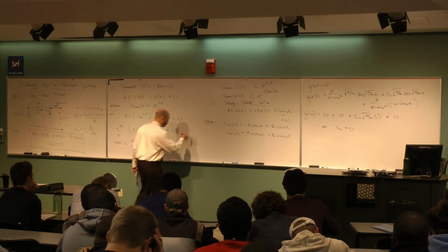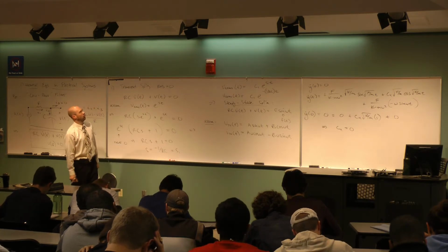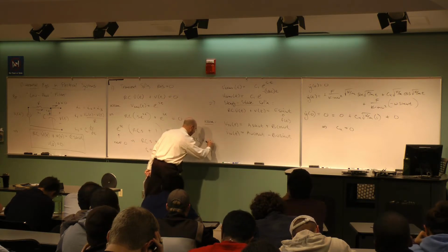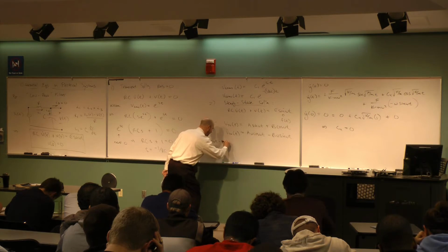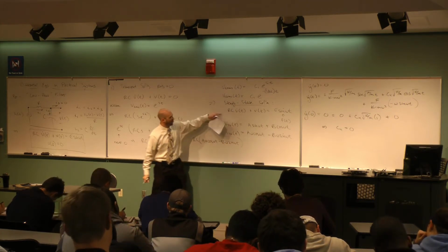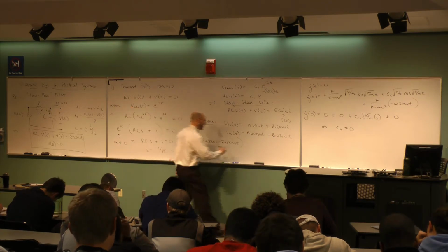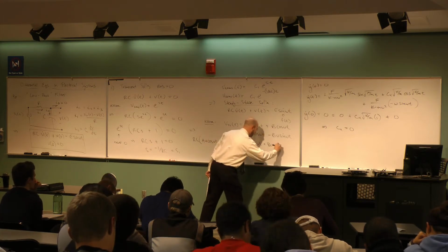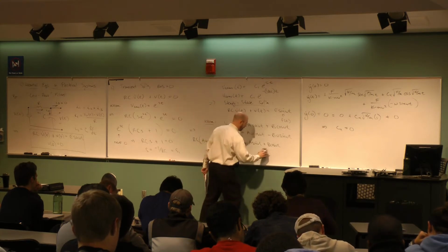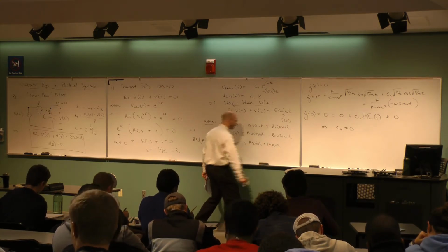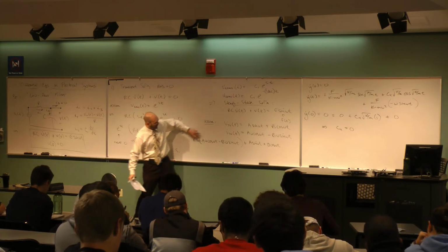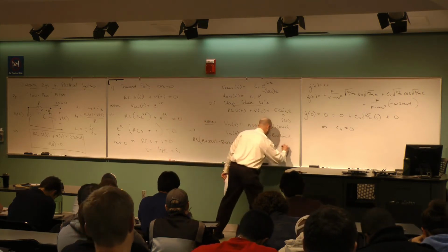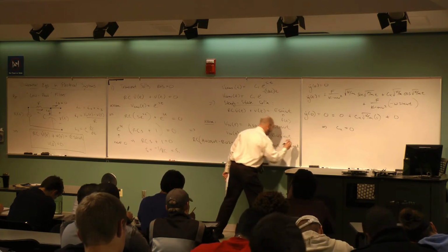Okay, and so what I need to do is plug this all into the equation. So it's RC multiplied by v dot. So that's a omega cosine omega t minus b omega sine omega t. Okay, that's the RC times v dot. Then I want to add the v. Well, the v is a times sine omega t plus b times cosine omega t. All right, so that's now the entire left-hand side. So this is RC v dot plus v itself, this entire term here. Okay, and that has to equal the right-hand side, e times the sine omega t.